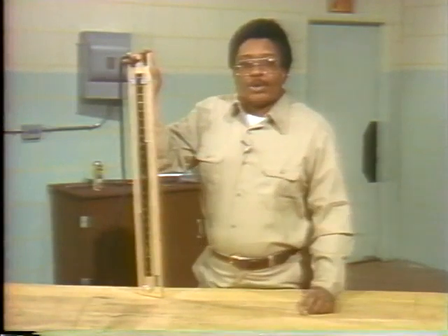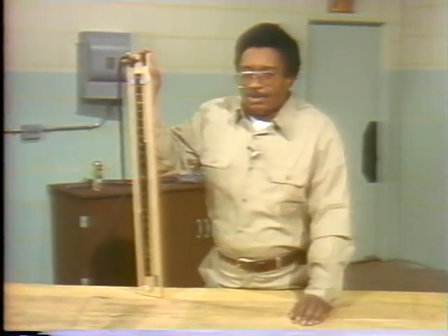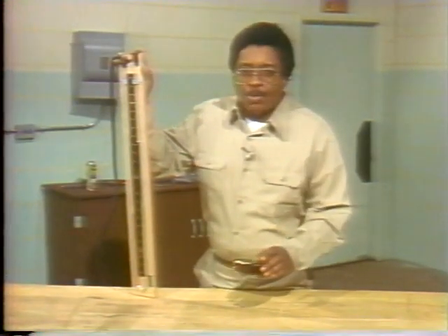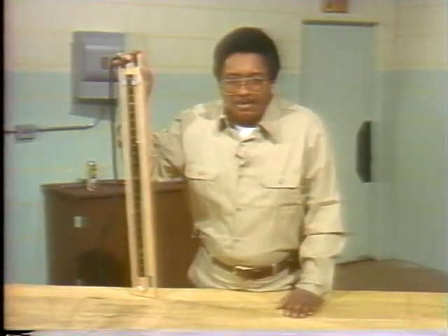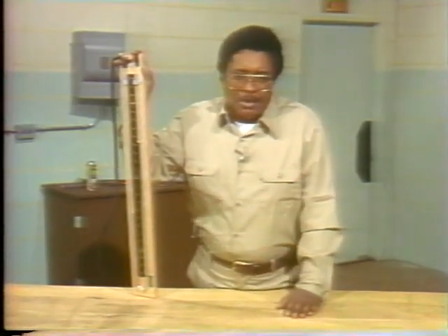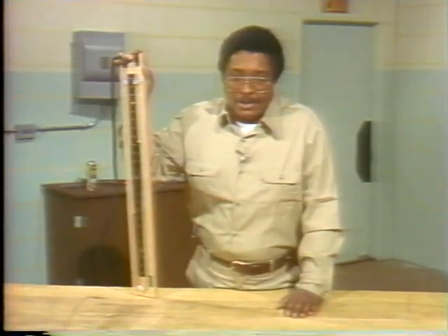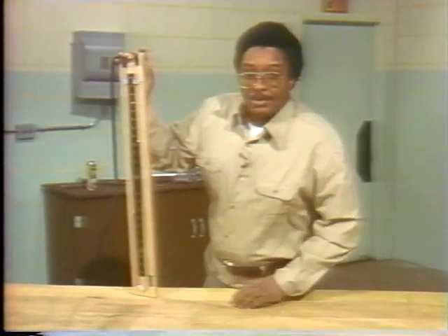The pressure is supporting a 9-inch column of mercury. To find out how much pressure the 9 inches represents, we multiply 9 times 0.5. Doing the math, we get 4.5 pounds. Pressure in the pipe is 4.5 psig. The reason it's psig is because one end of the manometer is open to the atmosphere.